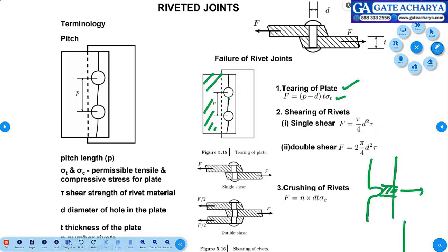Shortest span of time, heavy load. For example, an accident. This is nothing but an example of impact load. Whereas I'm just taking a hook, or say for example, this fan is not running now. I'm attaching this fan and I'm going off. An entire day it's going to hang. This is going to come under static loading. So please understand when to use what theories.